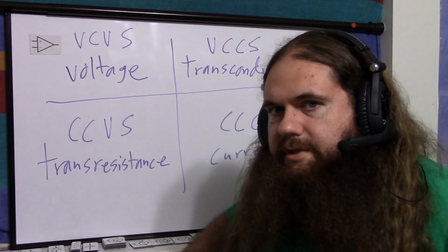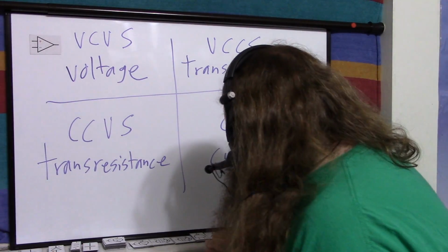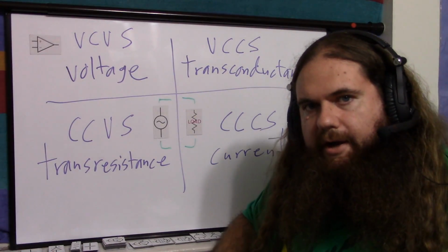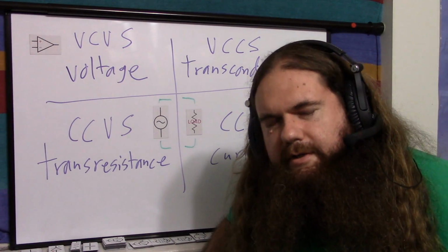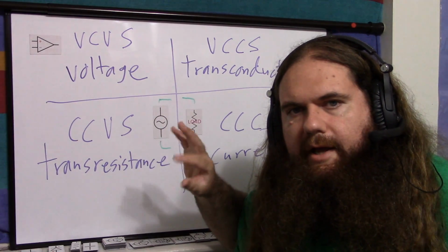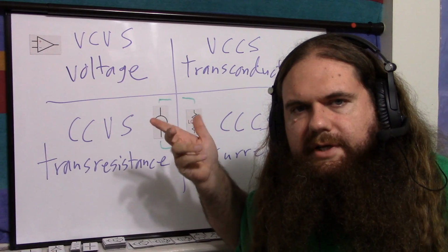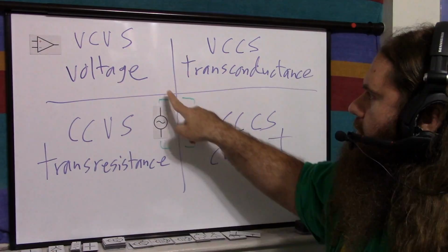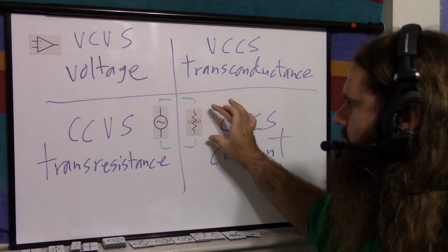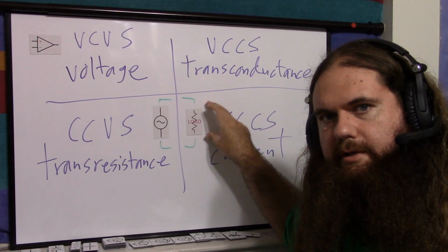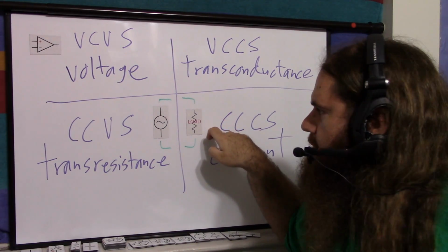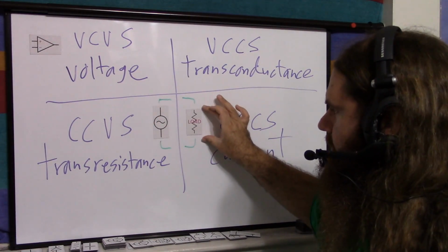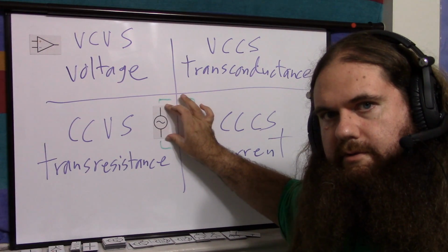What about the output? Voltage source, a voltage output. Remember, there's a load. We have a load and we have a signal source, and we connect the two together. The load can be an actual resistance or it can be an effective resistance, like a speaker might have a 6, 8, 12, 36 ohm impedance. So in any case, you apply a voltage, you have a resistance, and you get a current. What does it mean to have voltage in, voltage out? It means there is a certain voltage applied across this load. This load has a certain voltage drop. That voltage is proportional to the input voltage. Voltage out, voltage in means whatever the voltage for the load is, it's proportional to the voltage in.